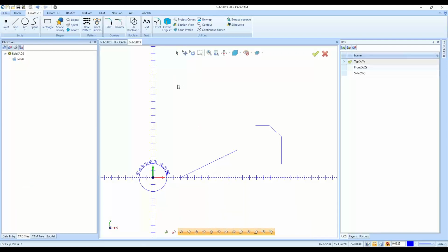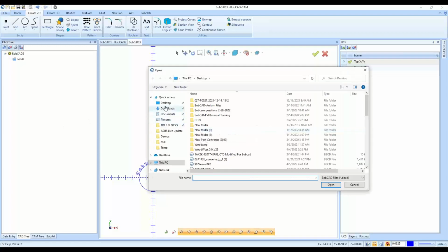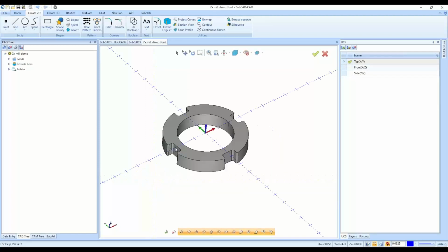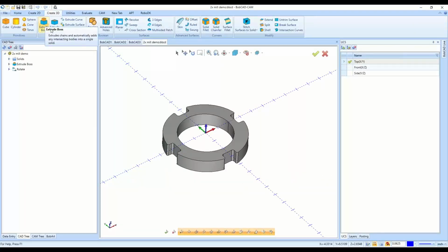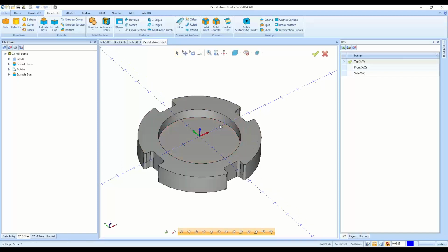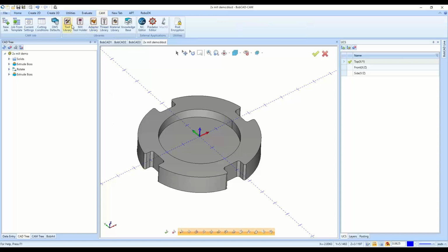So from there, we'll go to some different 2D CAD options, and I'll just select one of my demo files here for some basic 2-axis mill features here. So with this one, we'll look at profile and pocket operations, and to give us a better look at things here, we'll have an actual pocket in here instead of it being profiled out. And so once I've got my 3D model exactly the way I want it to look here, I can go to the top and go to CAM and start a new job.